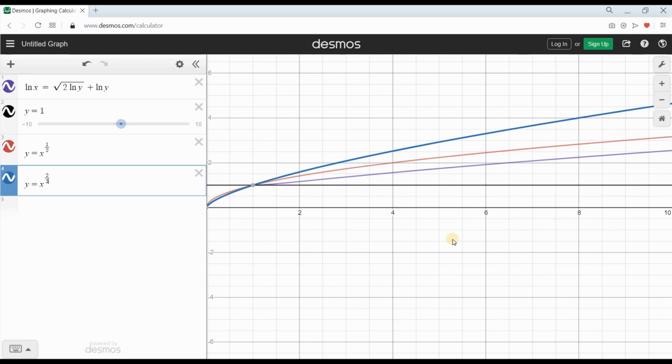Again, this is a transient or unsteady flow field, and as such, the path line is different than the streamline. And you can see that clearly here. That single particle that initially was at point (1, 1) will follow this purple line throughout the velocity field. However, at any given time, the streamlines that go through point (1, 1) look different, and we have 3 examples of them here in the form of the black, red, and blue lines.